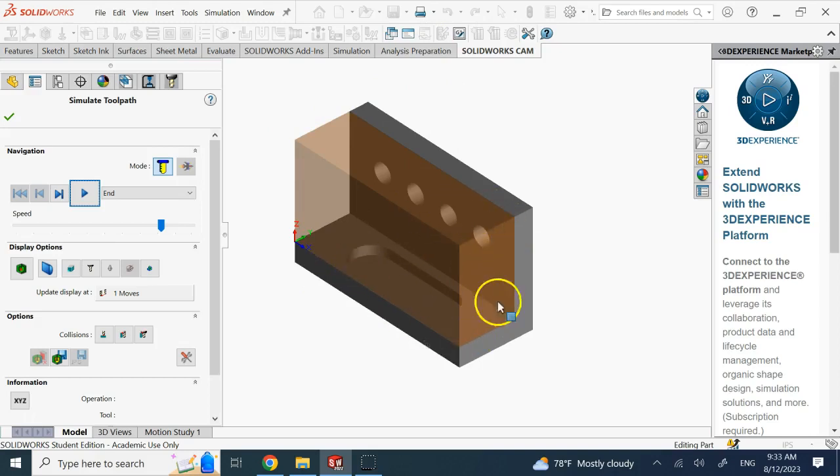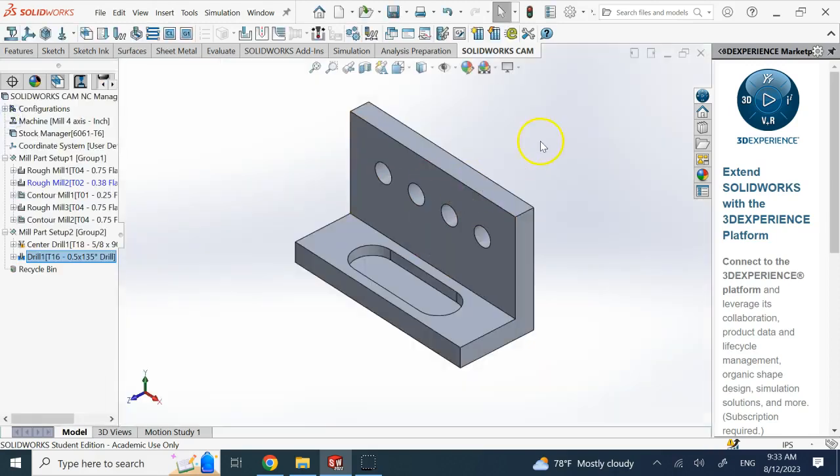It doesn't show that the part is being rotated 90 degrees, right? And it is instead rotating the tools for you, but you can tell that the tool was able to go in 2 different directions, up, down, and left to right. And in a milling machine, that is not what you typically do unless you have a table that is tilting. So this is done with a 4-axis mill.